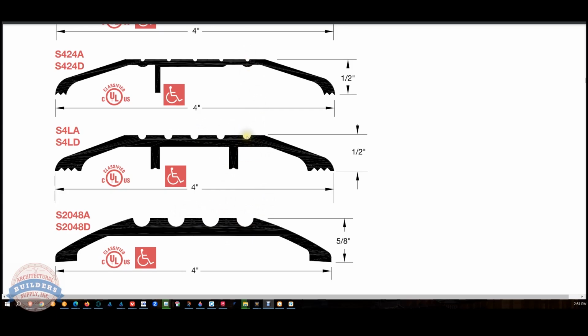But what I do believe is that the manufacturer is using the ball groove or the fluting as a means by which to use less aluminum. However, they're also obligated to produce a strong product. This is quite a thick extrusion. It's probably 1/4 inch for sure. This is probably 3/16. But you'll note when they get really thin and they flute, they're actually adding aluminum to the bottom of that. So there's clearly some science that they've learned.